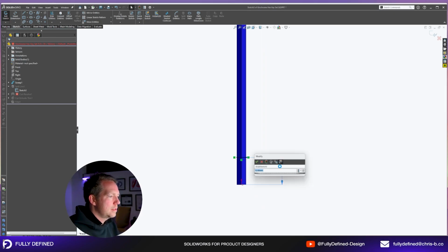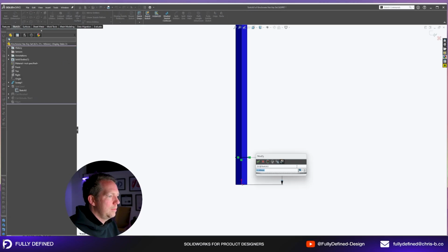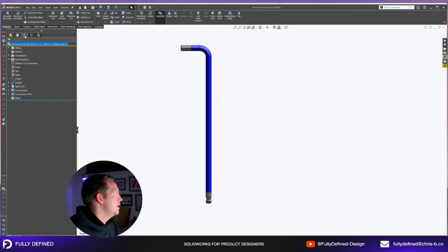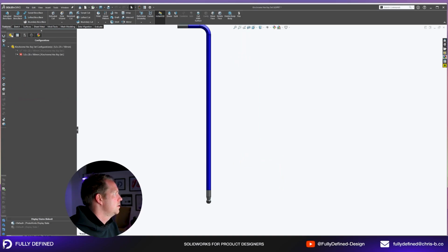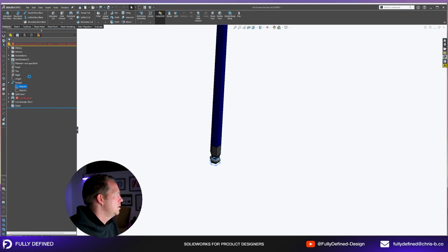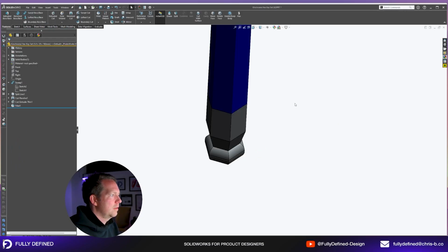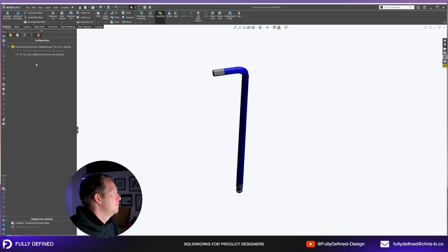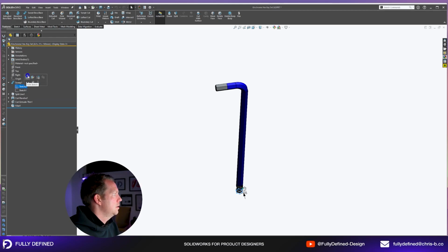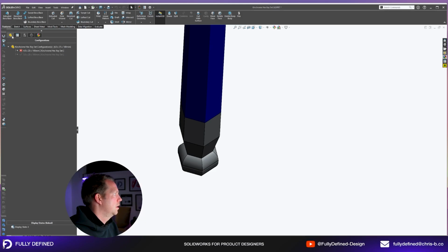So I'm going to edit this sketch here, change this configuration and change that to, actually, no, this one is 12. Just notice which configuration I'm in. I want to go to 4.0, and in this one it becomes 10. All right. So our error is actually in our original configuration. So I need to work out why. Now, could it be that we didn't properly change this dimension here? So for whatever reason, it became 5 in this configuration instead of 4. Let's have another look now. Okay, we want to edit this one, change it. In this configuration, it's going to be 4, 5, 4. Okay.